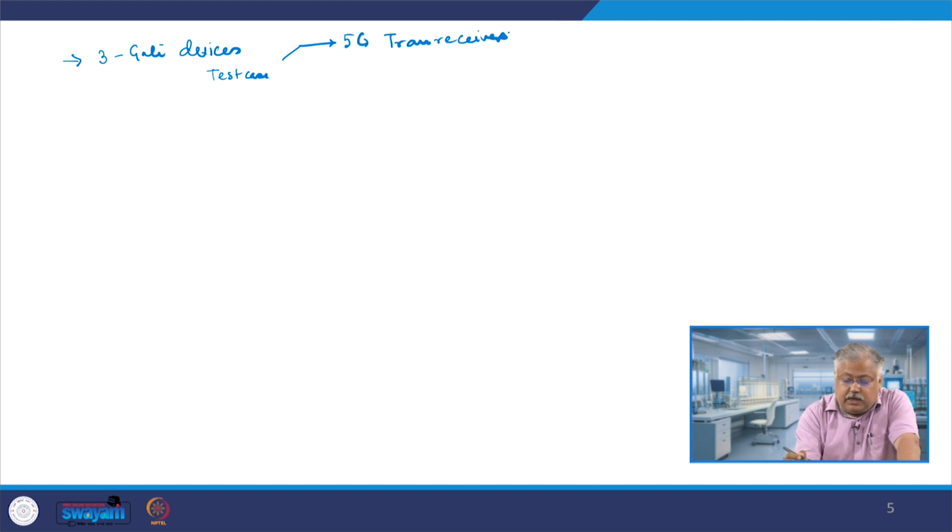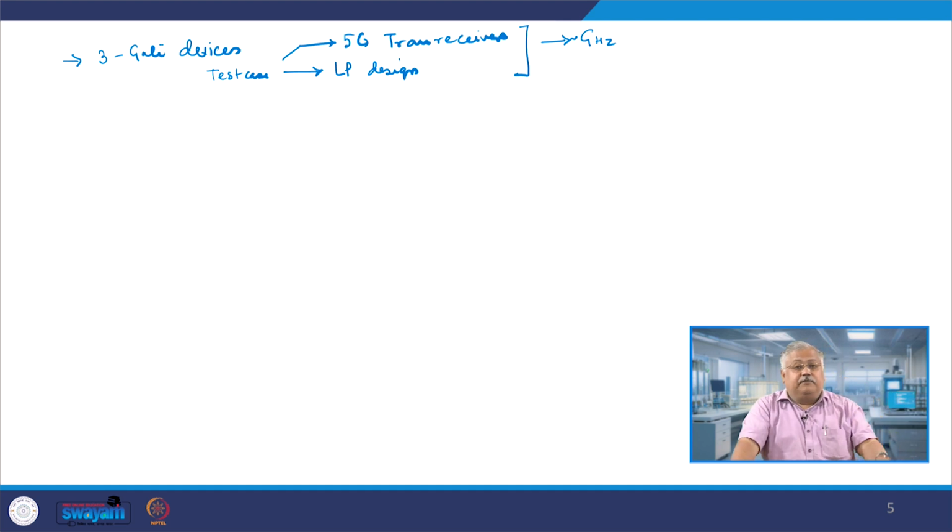And there we use FinFET for high frequency modeling especially, and then we typically look into other devices, for example low power design, and so on and so forth. So typically your frequency of operation will be of the order of few gigahertz, that is defined as a high frequency model which we are predicting for a FinFET based design.